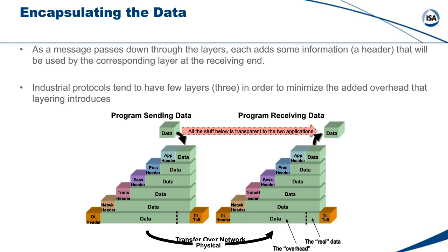Most modern industrial protocols, however, including those based on Ethernet, use only the bottom 3 layers for communication. This improves speed and throughput since the number of overhead bytes is greatly reduced. In fact, in most modern Ethernet implementations in process control, the bottom 3 layers are actually combined into one single layer, further reducing the amount of overhead.